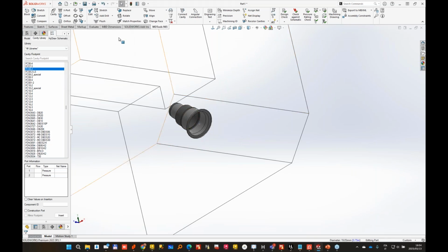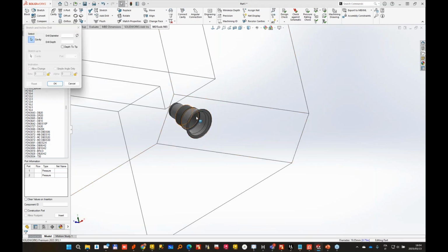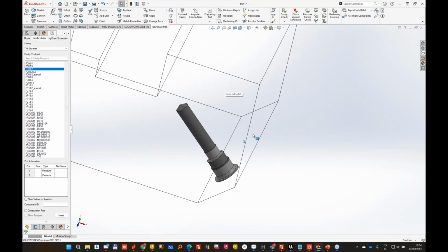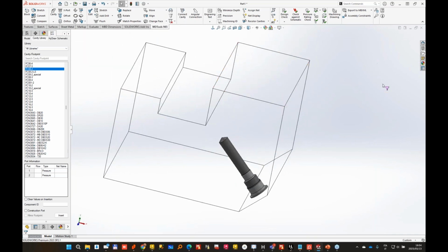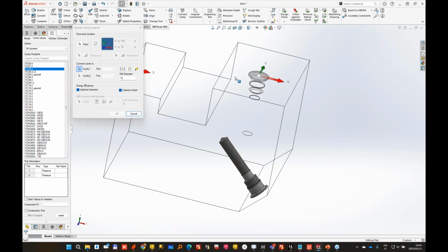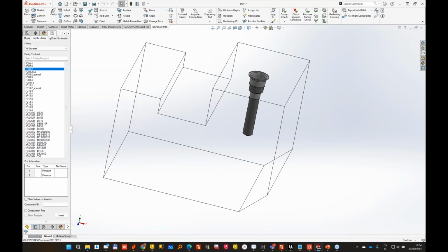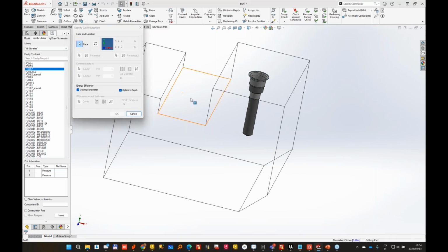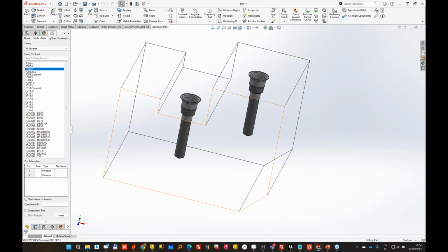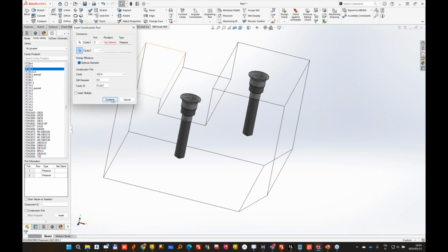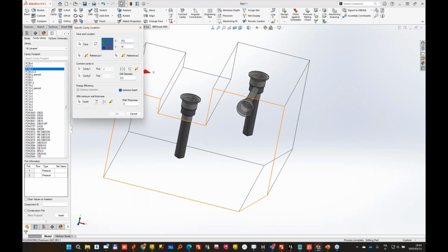Basically, here we can move cavities, we can stretch drills, and we can place drills in any non-rectangular face. As an example, I can change face and position the same drill on a different face, or I could copy and position on another face. Similarly, the commands for external ports and construction ports will work seamlessly.